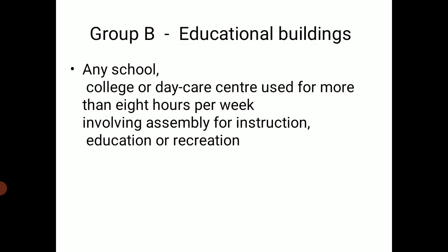Then Group B, educational buildings, that is, buildings meant for school, college, or daycare centers, which are used for more than 8 hours per week, and it involves assembly for instruction, education, or recreation. Examples for educational buildings include school, college, and daycare centers working 8 hours per week.